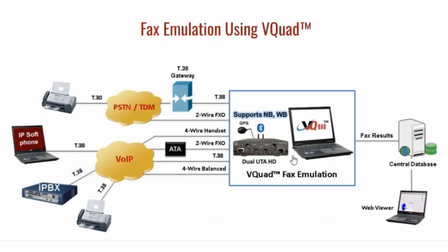The fax is basically just a TIFF file. We send the TIFF file through, it establishes a fax session, and then we receive a TIFF file at the end. So it's a true fax session. Now I'm showing that we're on both sides of the call. Obviously, we could be on one side of the call and the other side could be a fax machine. We support up to 33.6, and all the different data rates. So we can definitely support the fax machine, whether we're sending the fax or receiving the fax.